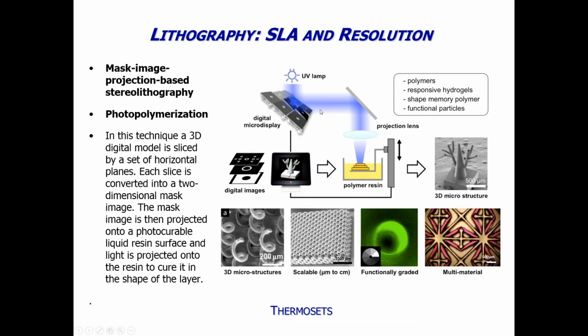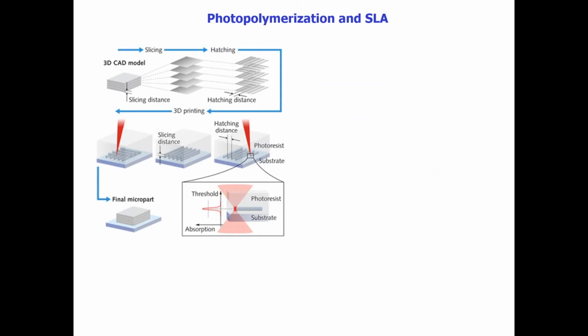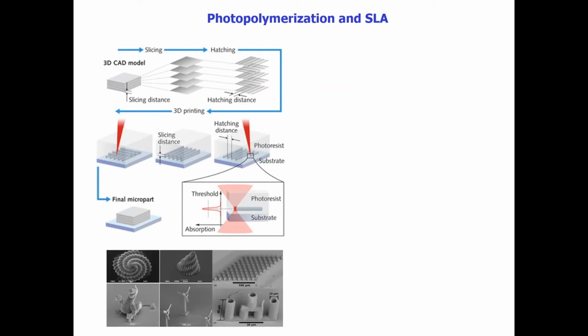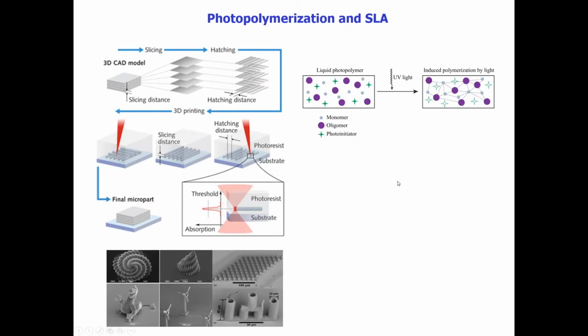So in an experiment, in an apparatus that allows light to be directed precisely at a specific plane, directed, let's say, by a micro lens or in a digital light processing apparatus. So a good example would be a projector, an LCD projector. Photopolymerization takes place selectively until you form an object out of that resin, and then you can rinse off the extra resin to produce the final object. So photopolymerization, as shown here, is eventually build-up of that cross-link or photo-cross-link material into various shapes and sizes all the way to the micron level, such that this is basically chemistry that was borrowed from the coatings industry.